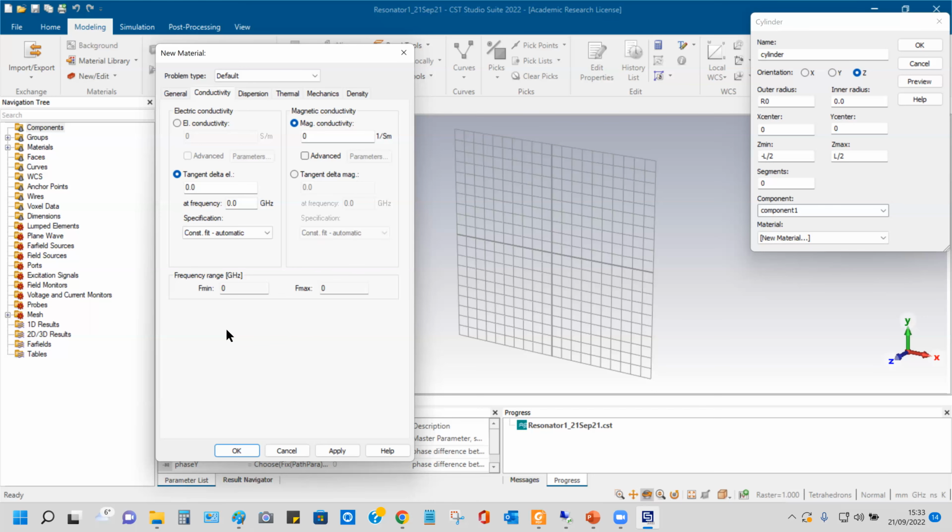If you have a too lossy substrate, then many frequencies can be operating. So that's why there is a substrate thumb rule. Not necessary for all patch antennas, but some thumb rule says that if you have a too lossy substrate, you will have higher bandwidth. If you have a thicker substrate, you will also have a higher bandwidth. Why? Because Q and bandwidth are inversely proportional, right? Q, quality factor. When you have a lossy material, you will have a low quality factor, thereby you will achieve higher bandwidth. So all these parameters boil down to this concept only.